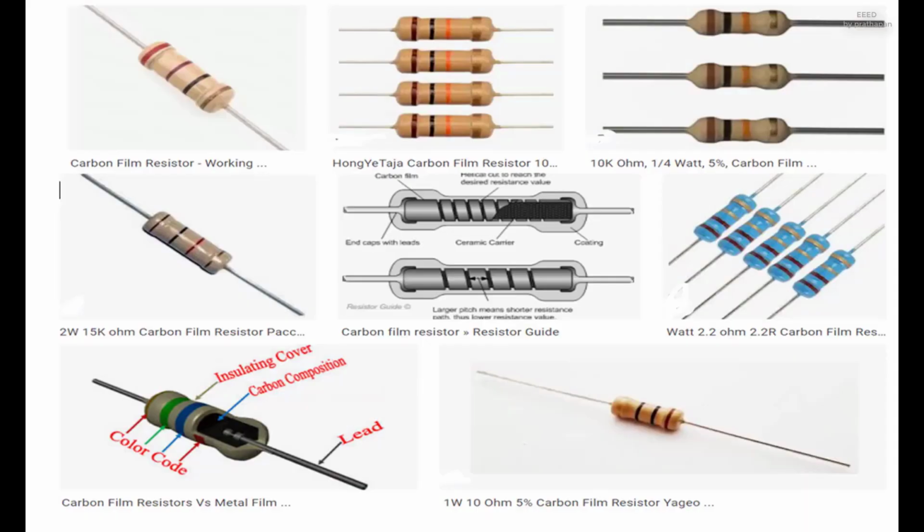A carbon pile resistor can be incorporated in automatic voltage regulators for generators, where the carbon pile controls the field current to maintain relatively constant voltage. The principle is also applied in the carbon microphone.